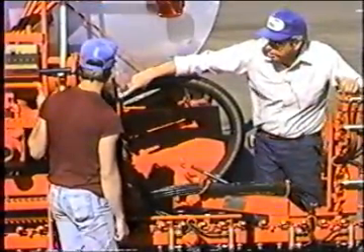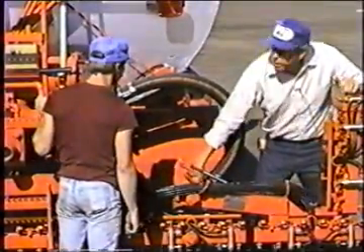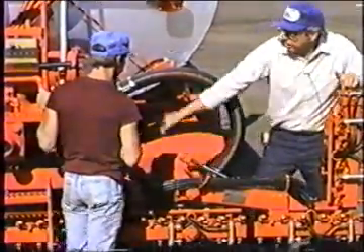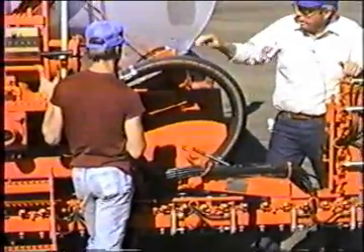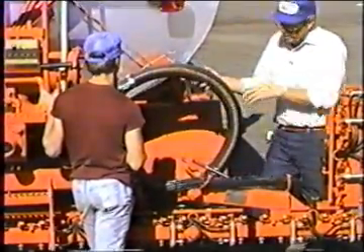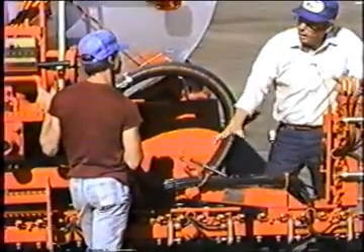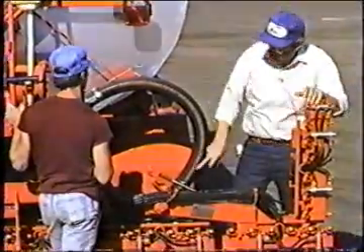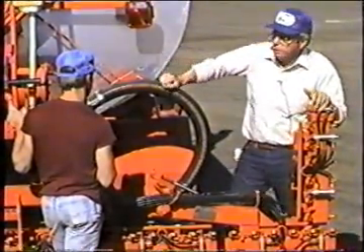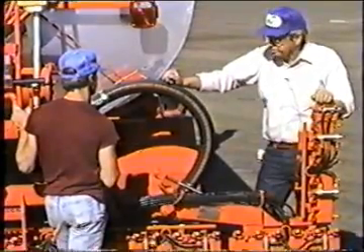You know, 3 of those swivels on the hose. There's the one at the top, one at the bottom, and one on the end of the hose. It's obvious what the top and bottom are. When the bar goes up and down, it lets the hose swivel up and down. The one on the end of the hose is so that when the bar is down and side shifts, it actually tries to twist the hose, and that prevents it from actually damaging the hose when it tries to twist it. It has to be free to swivel right there also.